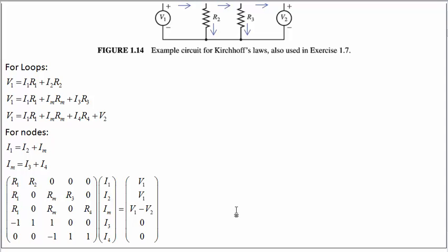If you're going to be solving it by hand, it's probably not the best idea to write these in matrix form, because the matrices end up being kind of sparse, so there's a lot of extra zeros that you'd be writing, and the numbers you're dealing with are probably complicated, non-nice integer values. So doing the math by hand is not as nice as it was with the matrices you were solving in first year. So most of the time for solving circuits, if you're going to be doing it by hand, it's better to just work with the equations, solve one equation for one of the currents in terms of the other one, substitute that into all the others, solve the next one for one of the currents in terms of one of the remaining ones, sub that into the remaining equations, and proceed until you can get a number value for one of the currents and then back substitute.